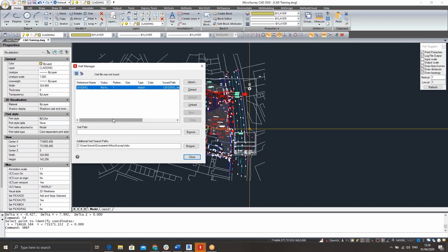So again, this would be quite common for designers or guys working on drawings to externally reference in different pieces of information, and they think they're transferring over all of the information, but they might not actually get it across to you. They might not remember to set it, or they might send you the full folder and it has an extra file in it. So we need to identify what is which. Generally, what I like to do is, if I scout around my drawing at the start and I realize I'm missing a bit of information, then I will return back to the drawing originator and request this information.